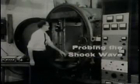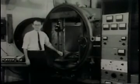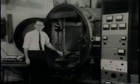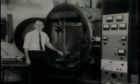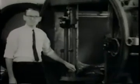We use this bigger wind tunnel for quantitative studies of rarefied gas flows. Right now we're going to take a closer look at the bow shock wave in front of a model which is in continuum supersonic flow. While we're at it, we'll learn something about heat transfer to bodies in rarefied flow. The model is a flat bar of aluminum.